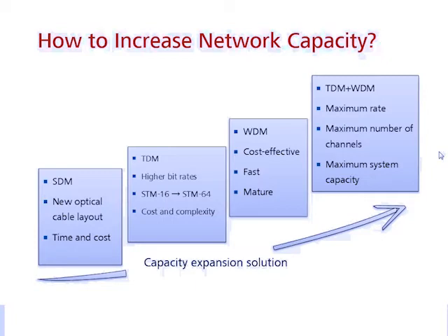For example, a few years ago, you only used STM1 capacity, which is not enough. You need to increase capacity. Then you can buy some STM4, STM16, STM64, which is higher rate hardware, to replace the old lower rate hardware, so you can increase the capacity directly.